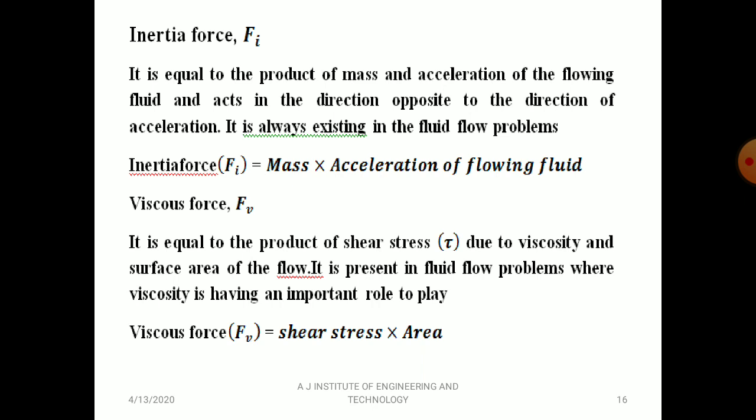Next, viscous force Fv. It is equal to the product of shear stress, which we already studied as tau in the first module, due to viscosity, and the surface area of the flow. It is present in fluid flow problems where viscosity has an important role to play. Wherever viscosity is important in problems, you have to consider viscous force Fv, which is the predominant force.